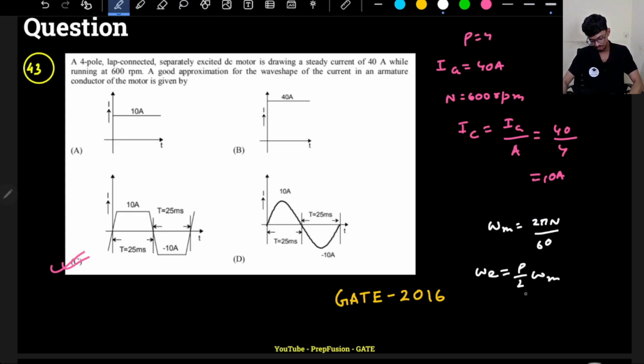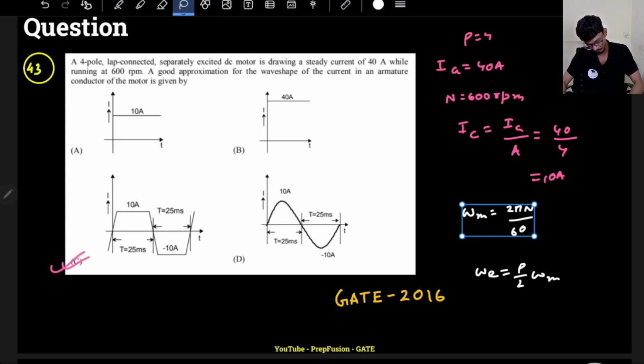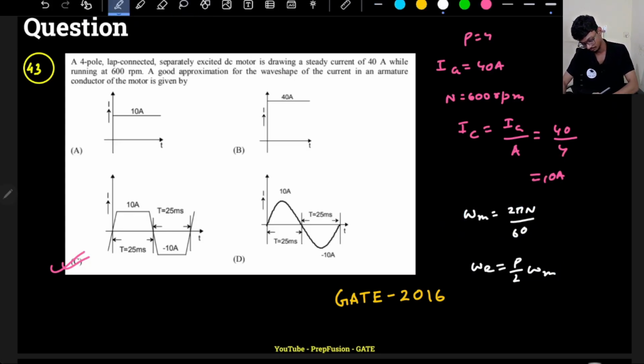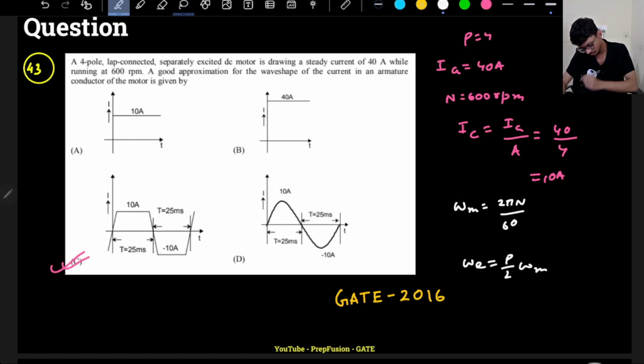Omega e is P by 2 omega m. P is basically 4, so 4 by 2 times omega m.